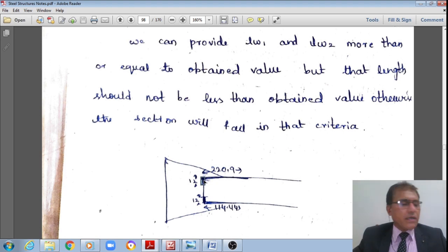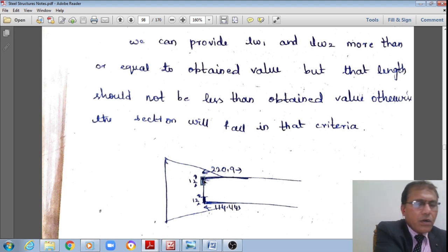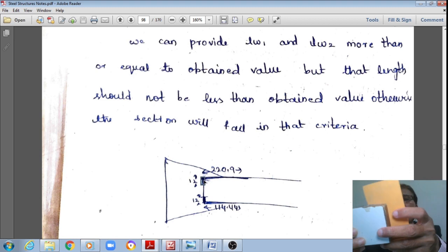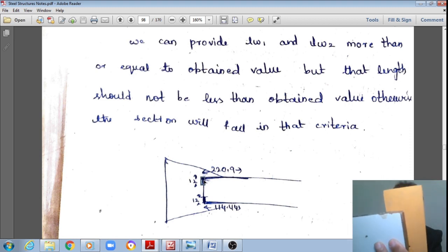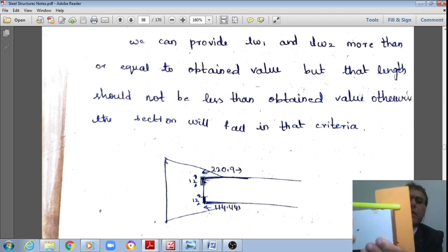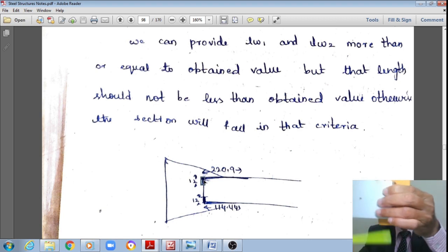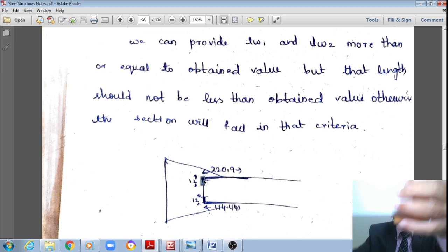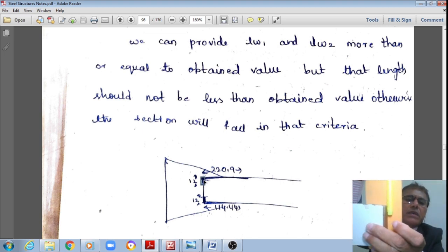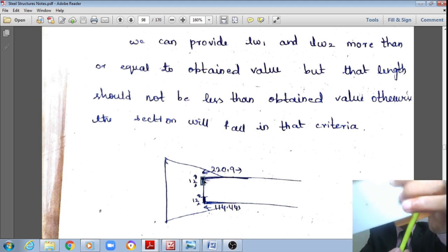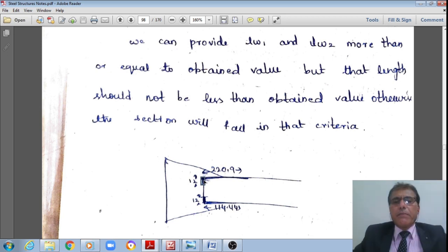Just now we already said that is how the overlap is. Like this. That is how at the top it requires 225 mm. At the bottom, 114 mm along with an end return of 12 mm and 12 mm here, right? Both 12 and 12 mm as shown in the figure.